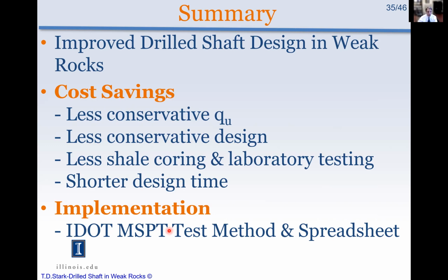So IDOT's implementing this through the MSPT test method I showed you, and this spreadsheet that I gave you a quick glimpse of. The spreadsheet plots the penetration versus depth graphs directly, and then it takes the slope of the linear portion directly. Both of those products or deliverables, the test method and spreadsheet, are available on IDOT's website, or if you're interested, I'd be happy to send them to you after this presentation.